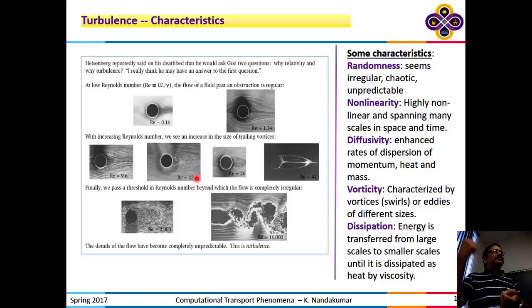Okay, so that's an indication that you are getting into instabilities, and we need to be able to understand the physical instabilities that drive turbulence versus the numerical instabilities that are realized through poor choice of your delta x and delta t. Okay, and once again that will become clear once we start looking at the discretization methods.